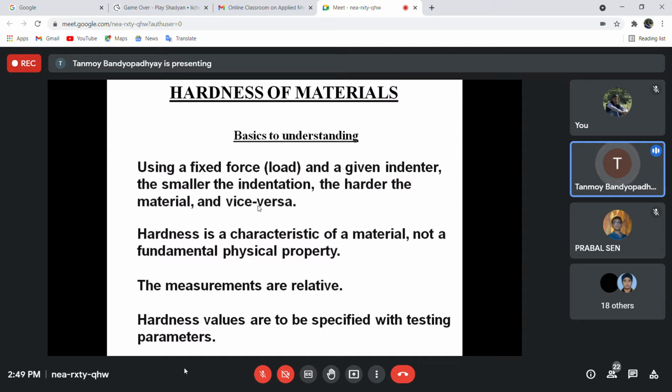But whenever I am specifying the hardness, it is something that may vary along the thickness of the material also. Suppose that we have some additive material. If I add some amount of carbon, we can make alterations in the hardness of the material. At a certain point, if it has a higher carbon percentage, that point will have a higher hardness.